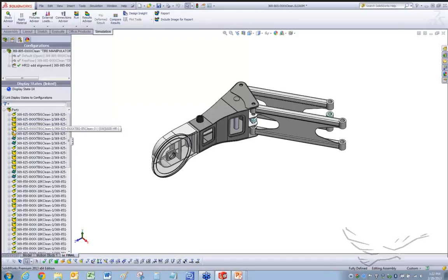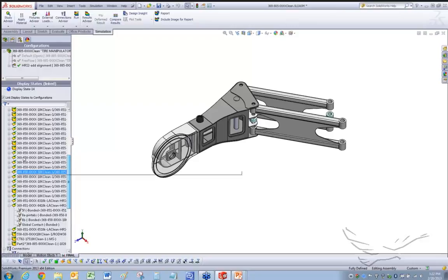You'll also see ones that look like surfaces. Those are the ones that are automatically generated as shell elements. Those are basically surface models inside the analysis. So if we go and take a look, you'll see that all of these have basically automatically been defined based on the type of geometry that they are. Sheet metal features are automatically shells. Chunky, blocky parts are automatically created as solid.